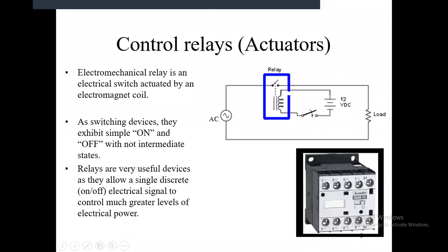We discussed the control relays. They are important. Within a control relay, we can say there are two parts. One part is when you excite the relay. The other part is when the contacts are made. So what was the benefit of relay? A 12-volt relay can operate a 120-volt or 240-volt device. So this is one benefit.